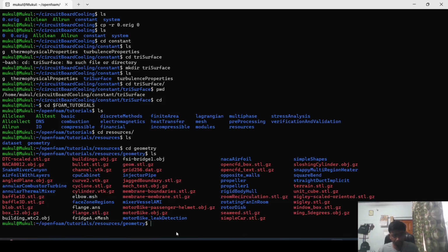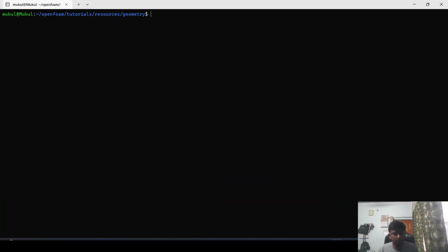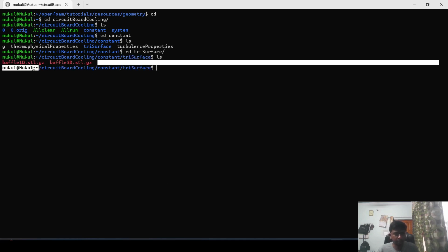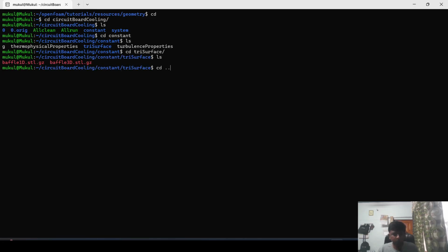Okay, so we have to copy both of them, cp -r baffle1D baffle3D, and we will paste our path wherever we have to paste it, and enter. Okay, I will clear the terminal, press cd, then again I will go to circuit board cooling, I will go to constant, then I will go to triSurface, and here we are, our files have been copied here. All right, so let's go back.